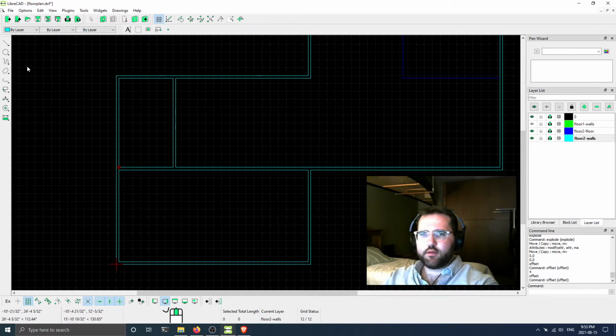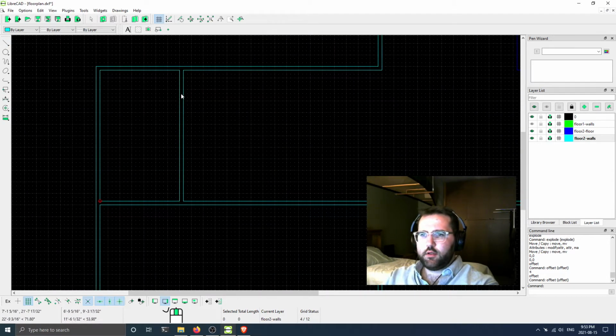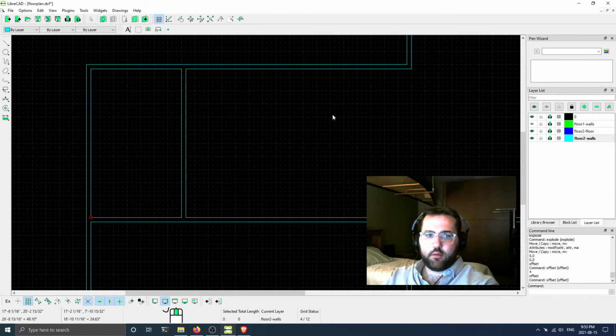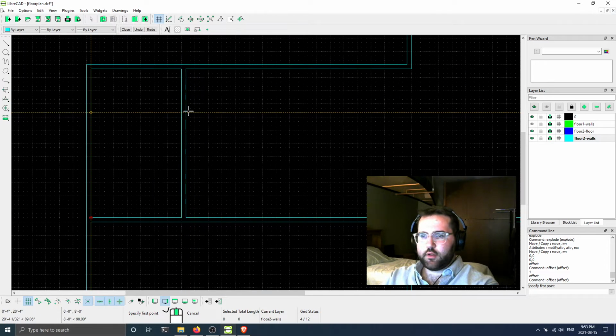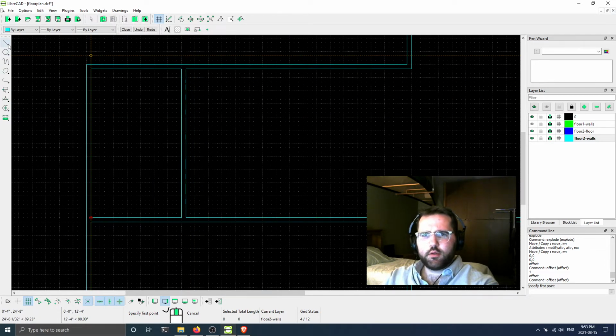Yeah, that'll work. So how about we want to keep a hallway probably about 6 feet wide. So we can look at that here. That'll end up being probably about a quarter of the length, or half the length here. So let me turn on endpoint snap.